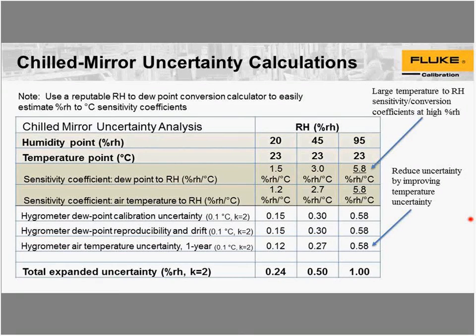But for relative humidity, you have to cover the range of temperatures and the range of humidity. So the RHapid-Cal, for example, we are calibrating it at 14 different combinations of temperatures and humidities to make sure that we thoroughly cover the temperature range and humidity range.